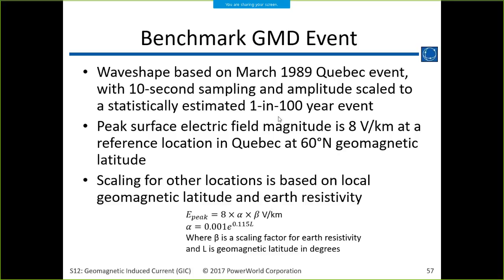We probably need to update it too, because it uses the single snapshot mode that you load in with an auxiliary file, and then it can produce a time series for the transformers. It's not directly compatible with the transient stability tool, so we probably need to put in a new version that will work with our transient stability tool. But it will work with the power flow, and it can still give you a time series for transformers if you want to put those into a thermal model.